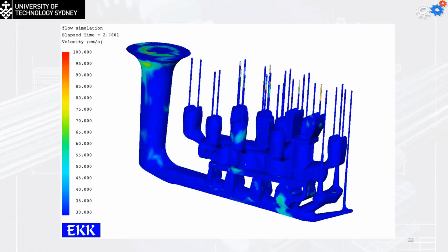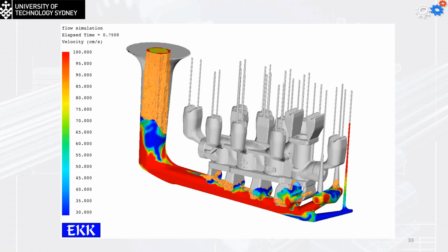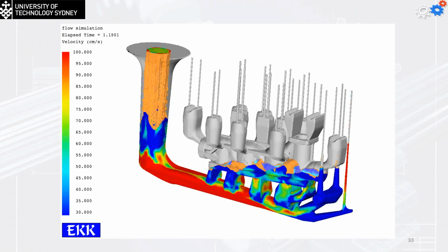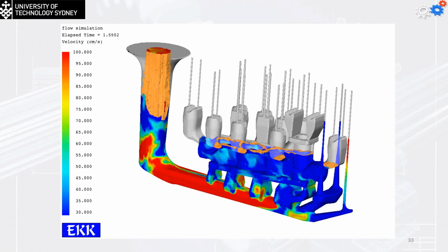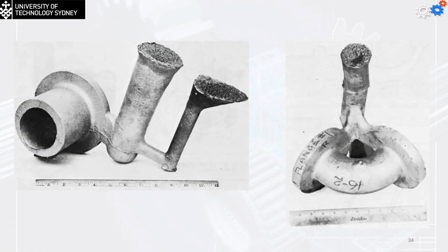Obviously, this one shows you the whole thing. So we had the core inside this one. We used the pattern to make the cavity. This is the riser. This is the pouring cup. This is the downsprue. This is the runner. Same thing here. This part should be trimmed. We have to take it off, recycle it, and do some finishing work on the cast part.